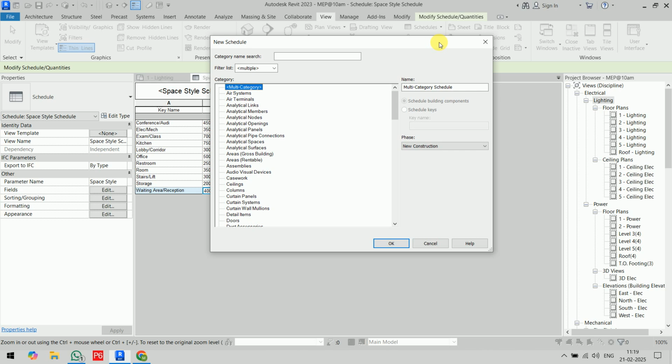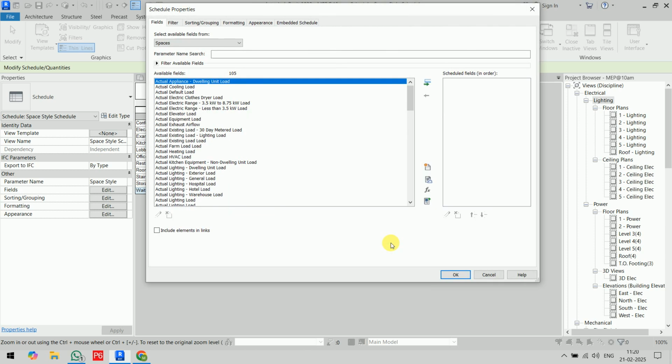Now we have received the required values. Now we can compare the required lighting with the average estimated illumination, because average estimated illumination provides the value of how much illumination we have placed. So we go to Spaces again and create a schedule named lighting analysis. Give it OK. This will open up.